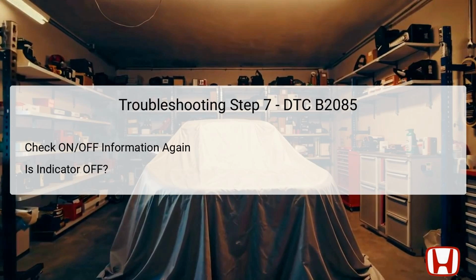It is critical to ensure that the switch is actually faulty, instead of other electrical systems causing the issue. If the switch were to function correctly in this state, it would indicate that the problem lies elsewhere in the circuit. Documentation should be done diligently at this stage to facilitate effective component replacement and future troubleshooting.